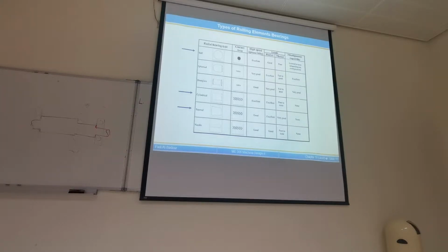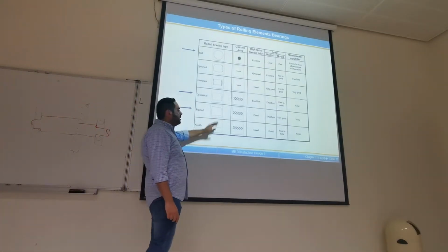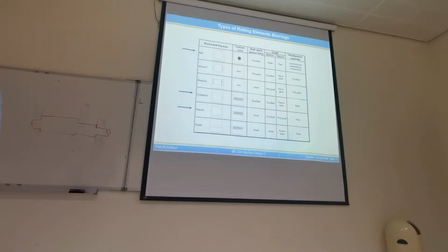You can have a radial load of, let's say, 2,000 Newton, while the thrust load is in hundreds of Newton. Ball bearing can take care of that. Because the thrust is going to be in this direction, so the ball cannot orient itself 100% to take the thrust load. But for tapered roller bearing, because the rollers are inclined, the surface of contact is inclined, so it can carry the load. We'll do some sketches soon to show the difference.